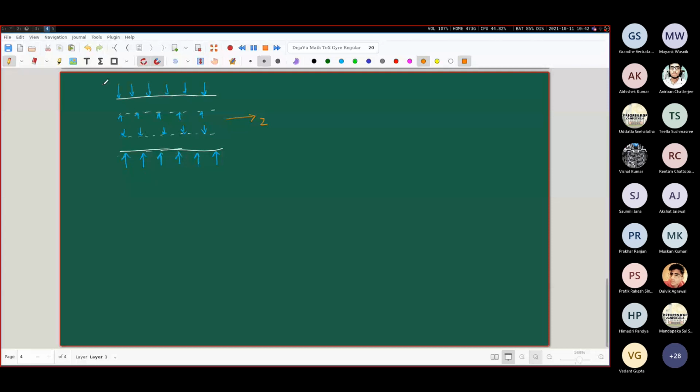So remember that this is our radial direction. So the pressure is perfectly along the radial direction. There is no component of the external force or pressure along the z direction. So both these conditions that are required for a situation to be plane strain, that is satisfied.